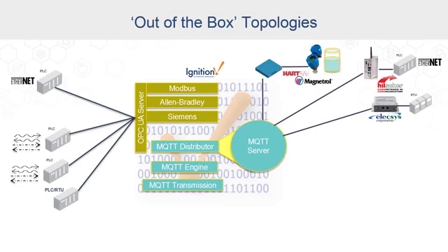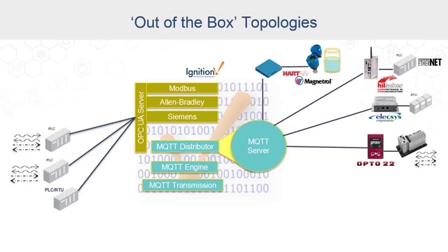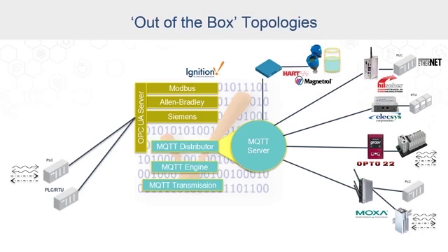Take that EtherNet/IP or Profinet information and publish it using the Sparkplug specification into MQTT. So that device might be able to migrate out. Opto 22 has implemented MQTT with their groov and their extensive line of optically isolated I/O. So that might let me replace a poll response with a native publish and subscribe architecture.